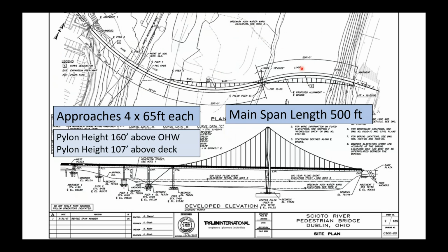There we go. So in plan view, the curved deck means that the main cable is on the inside of the curve, and all of these hangers are pulling the deck towards the inside of that curve. And here you've got the main cable anchoring at the top of this column, and this entire span of the deck is being pulled towards the inside. So the tie-down cable we took and we carried back across the bottom, underneath the deck, and anchored it on the opposite side of the deck so that we could balance the lateral load on this pier, pier 5 in this case.